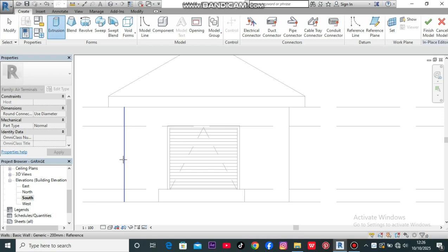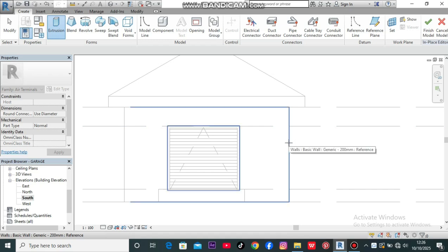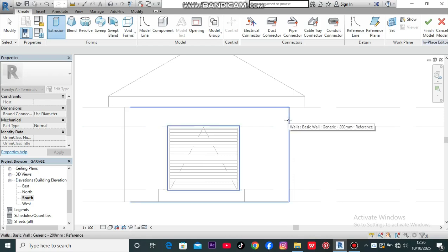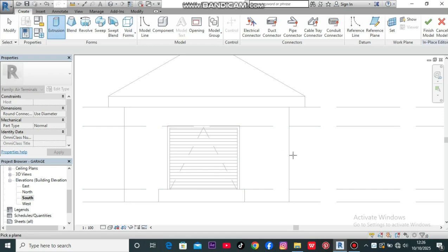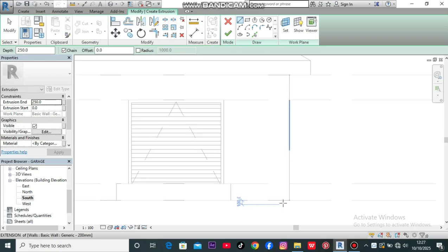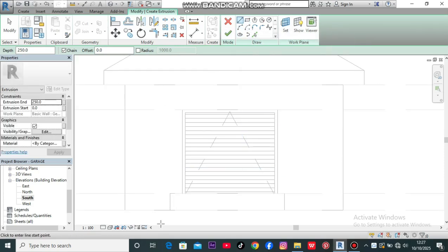So this is telling us that it wants to select the wall that's constructed there beside. That's from another view. And when I come here, same to this side wall. What if it changes to this, 1 2 3 4 5 6 7 8 or almost 9 lines? So this is telling us it's the wall in front that I want to select. So just stay down here. Once you have more than one line, sometimes it gives an L shape, sometimes a U, it depends, but just make sure you have more than one line down here. Then left click there, and then you could design whatever you want.